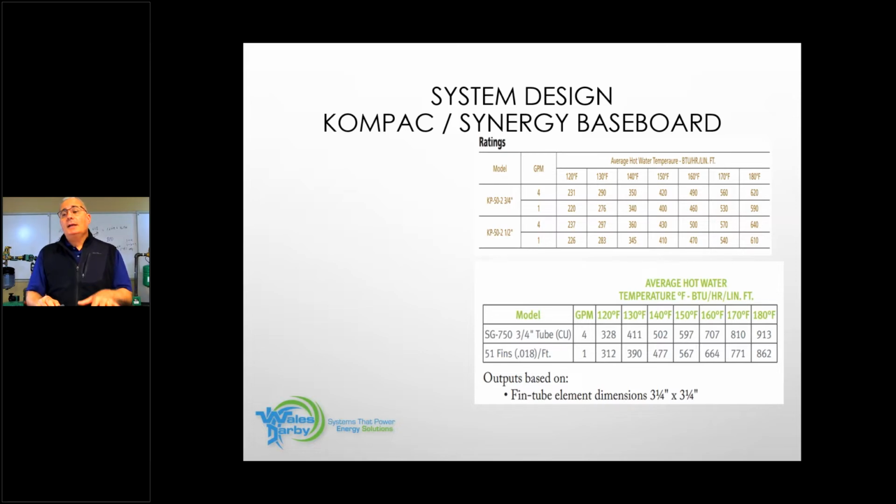But I don't want to run my combi boiler at 180 degrees. I want this boiler to condense. So go to your questions and type in, what return water temperature do we need in order to make that combi boiler condense? I'll give you a couple of seconds here to type that in, and you guys let me know. 130, 140, 120, 135. Gas or oil, doesn't matter. Okay. They're all landing in the same area. Everybody's got the right idea. So if you answered 130, 120, absolutely spot on. 130 is the mark we want. If you weren't sure, that's what we want.